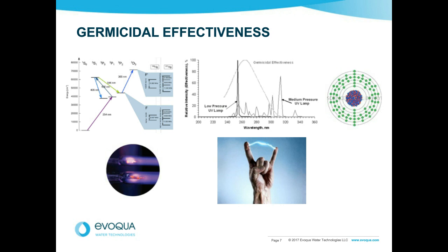Great, thank you. We have a few more questions left. What is the typical life of a lamp, and what can affect the lamp's life? Well, what affects it is starting and stopping. If you want to have perfect lamp life, then never turn it on. People will turn them on. So what I say is, if you must turn it on, don't ever turn it off. If you can leave the lamp on, from a low pressure lamp, you'll probably get 2 years. You might even get 20,000 hours of life from a low pressure lamp.